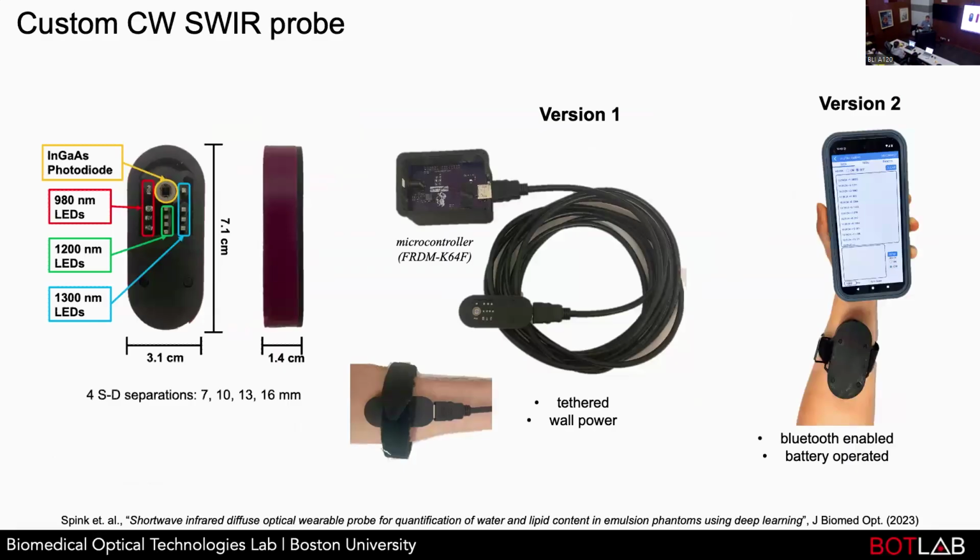Oh, sure. It doesn't take any more time, but part of it comes down to practicality. So this InGaAs photodiode, first of all, it's a few hundred dollars, whereas the LEDs are just a few dollars. And the reason it's a few hundred dollars is because the InGaAs technology is at a much earlier stage than silicon technology. And this is a relatively large active area InGaAs photodiode.